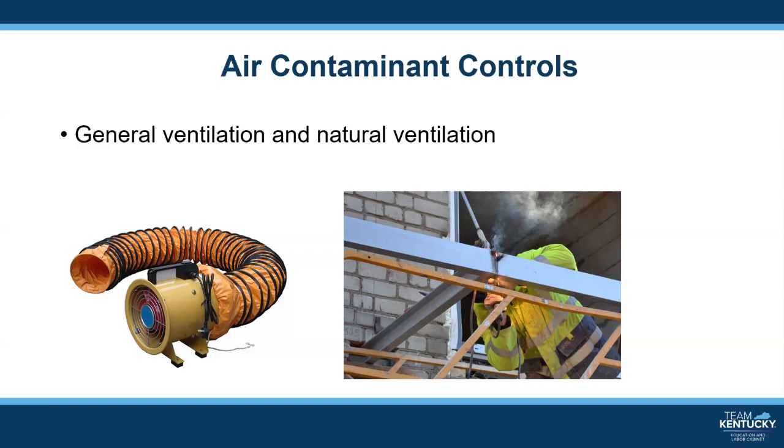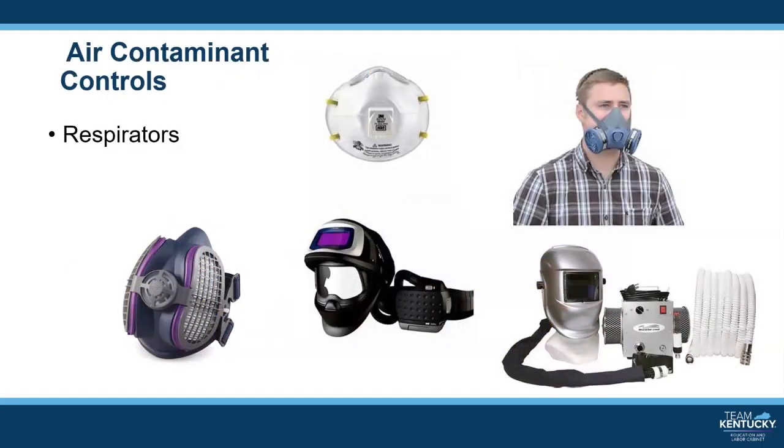If you're welding outdoors, you would want to place yourself such that natural wind is coming from behind you so that the welding fume smoke is blown away from the breathing zone of the employee. Part of the air contaminant control measures might be the use of respirators. Here are some respirator pictures.